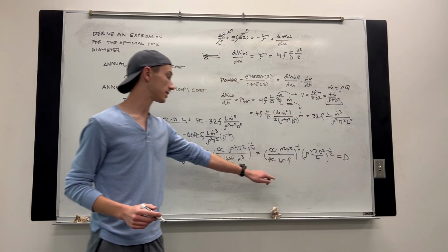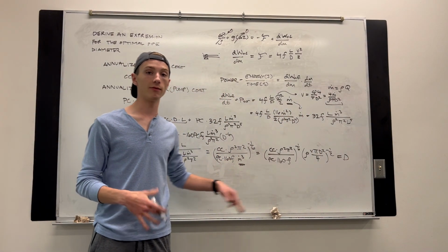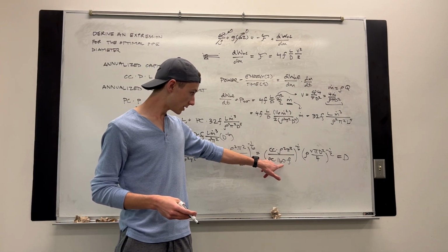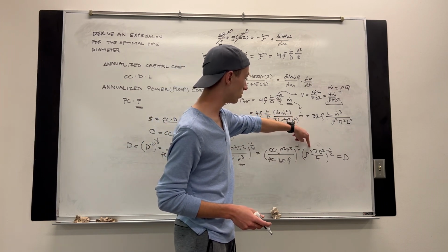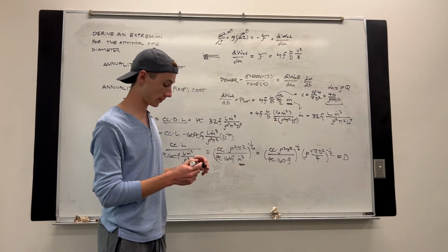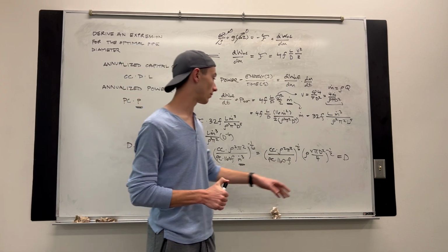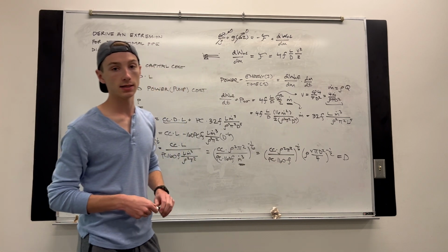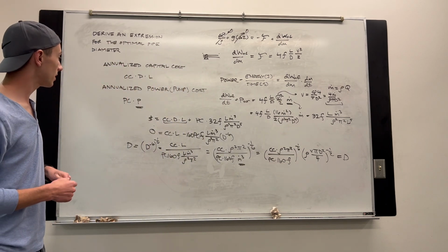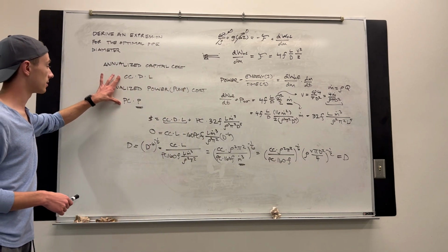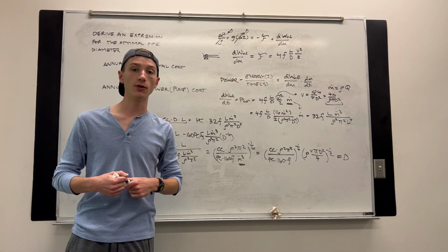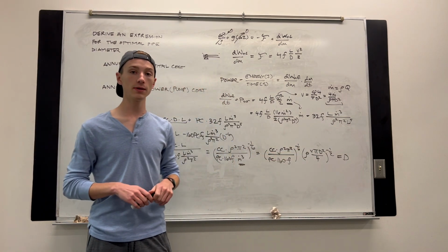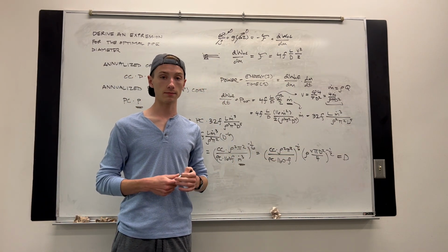Now, what's really unique about this, the reason I had us bring mass out, this flow of mass with respect to time, is because when we change this to velocity, we can actually solve this for velocity, because you can see there's d on both sides of the equation here. We end up solving this for velocity. And what's really interesting is even as these capital costs and pump costs change with the market over time, the optimal velocity will pretty much always stay about 2 meters per second.